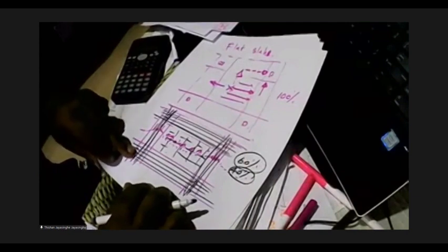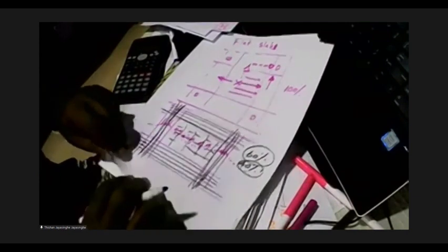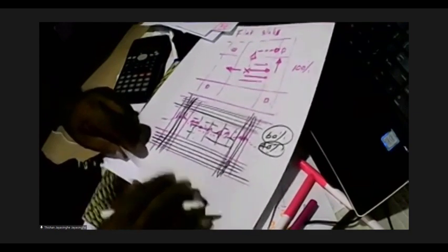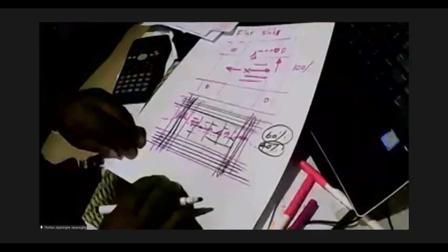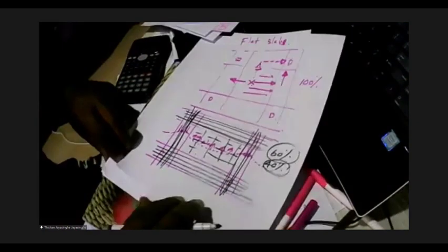And with experience and more testing, they found that putting the concentration of reinforcement, the pre-stressing tendons, in both directions is not necessary. And there is no need to consider this type of situation in PT slabs. You can go for a much simpler system. What is that system?